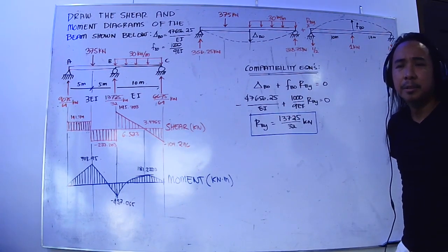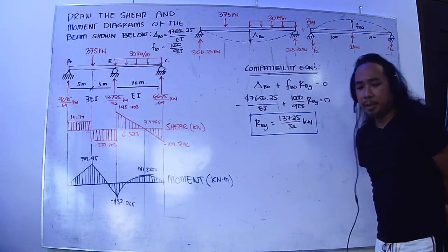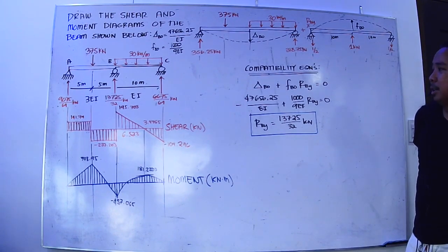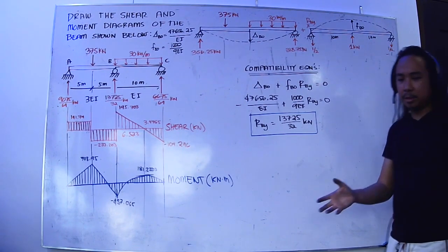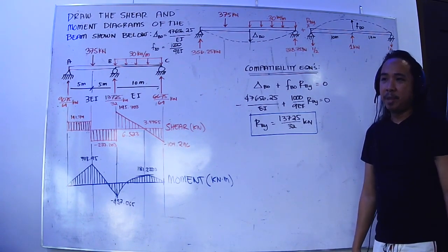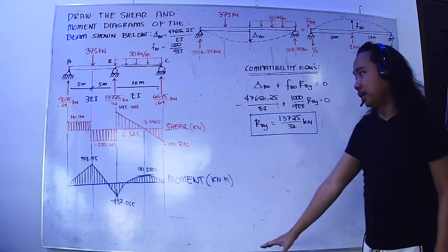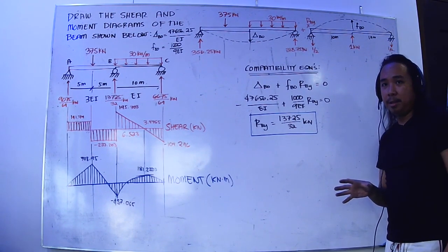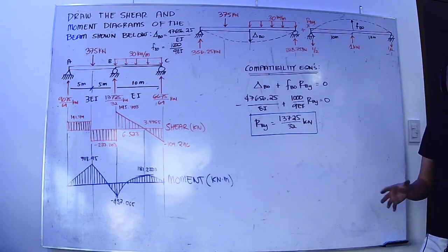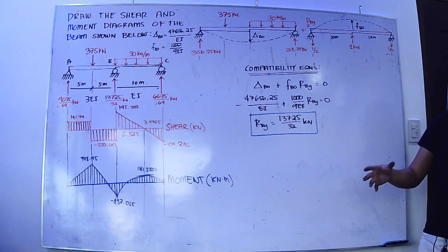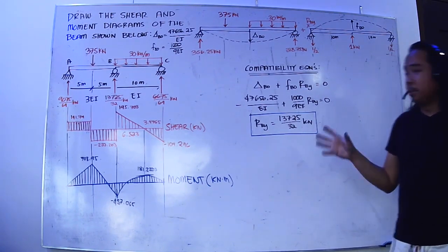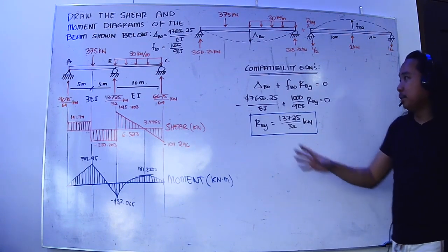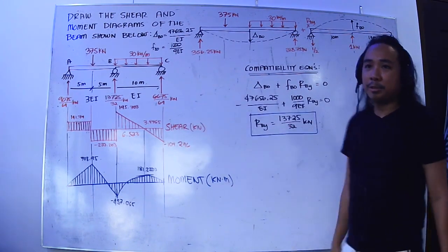It is cumbersome, a tedious process. But the goal, once we get the shear and moment diagrams, is to find the maximum shear or maximum moment, and those are what usually dictate the design. Deflection is another parameter. But in this way, we are obtaining shear and moment from those deflections. You can use this when you design structures like houses.